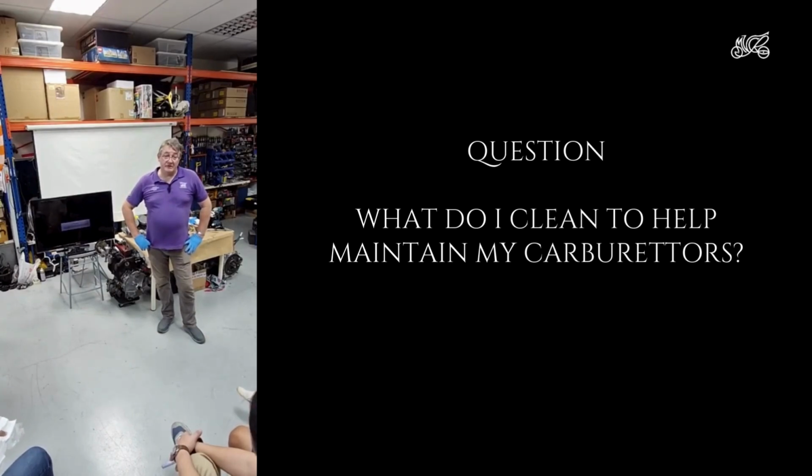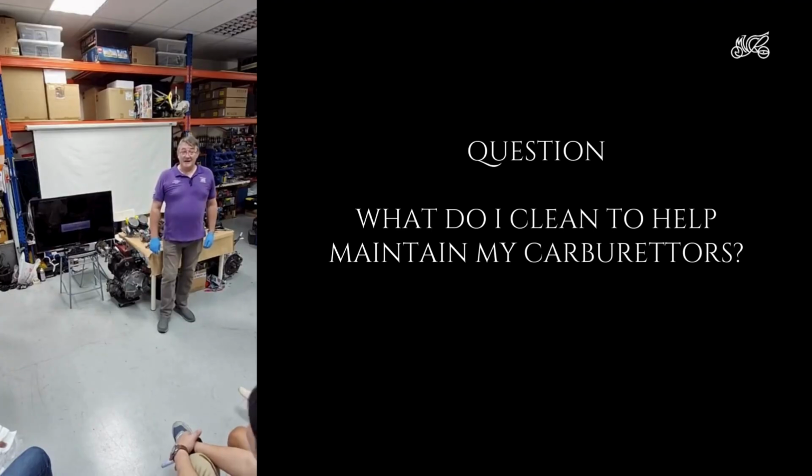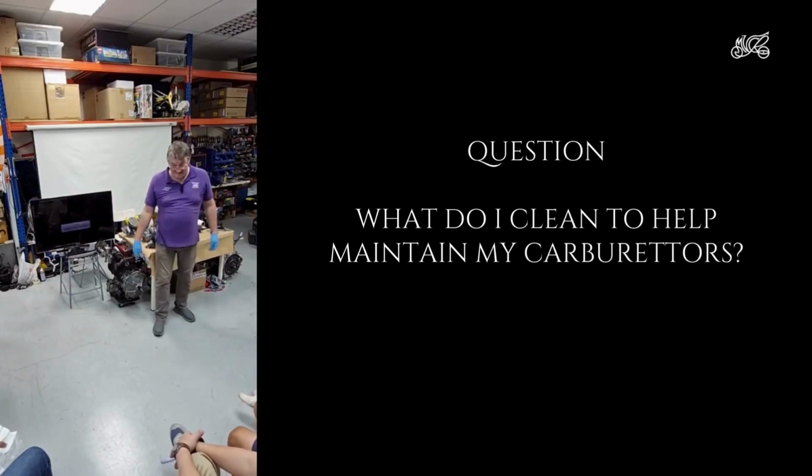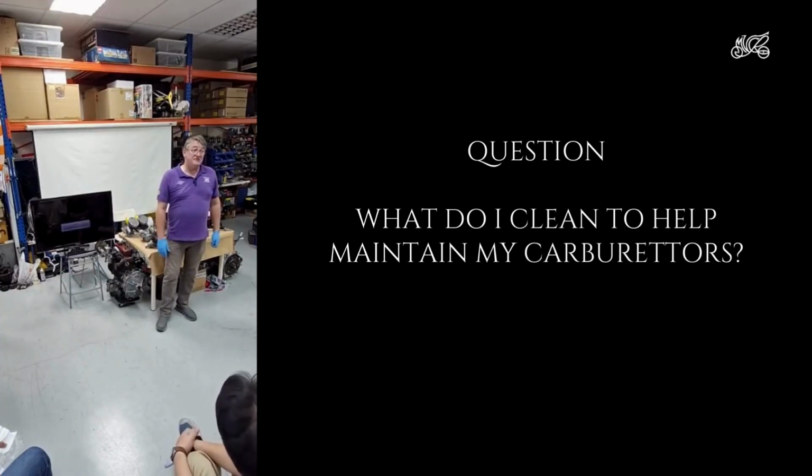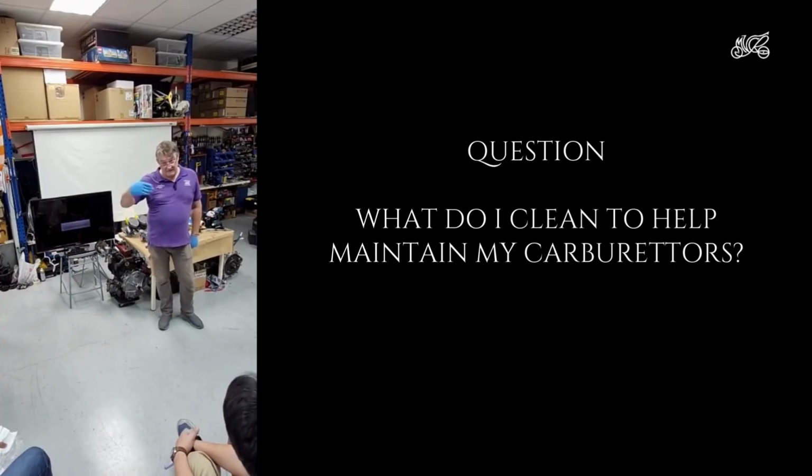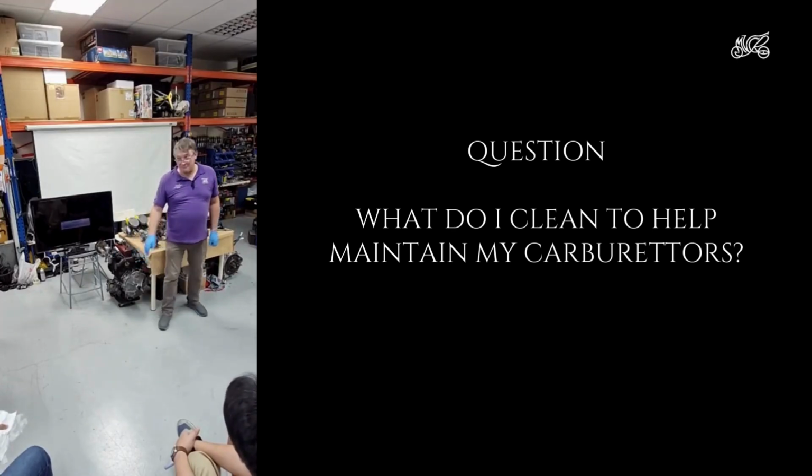But with all these things, the Italian tune-up is also very powerful, right? So just get in your car and drive it hard on the highway. And actually, it's designed for that. And it surprisingly cleans up a lot, especially deposits on valves and in the induction system, cleans it up a lot. So it's not an old wives' tale. It really does make sense. If it's not running right and you've just been poodling around town for 6 months, get out on the highway, floor it for half an hour. It'll be much better. Yeah.